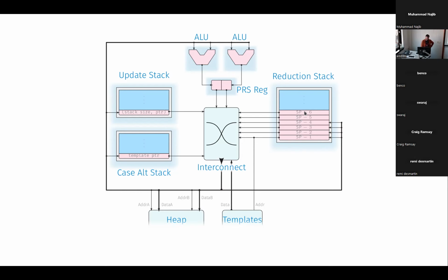And one more trick to widen that bottleneck a little bit further is having parallel access to each memory. So for the heap memory, in this example, we have two independent ports, so we can do two wide operations at the same time. All of that is really quite basic stuff, but it requires you to have a properly custom processor design.